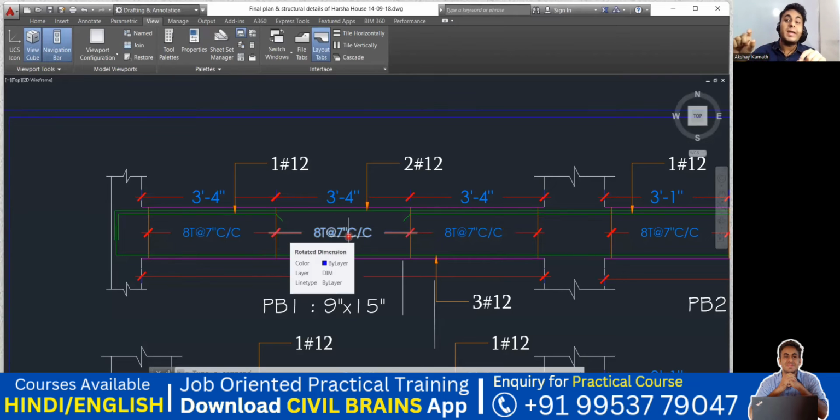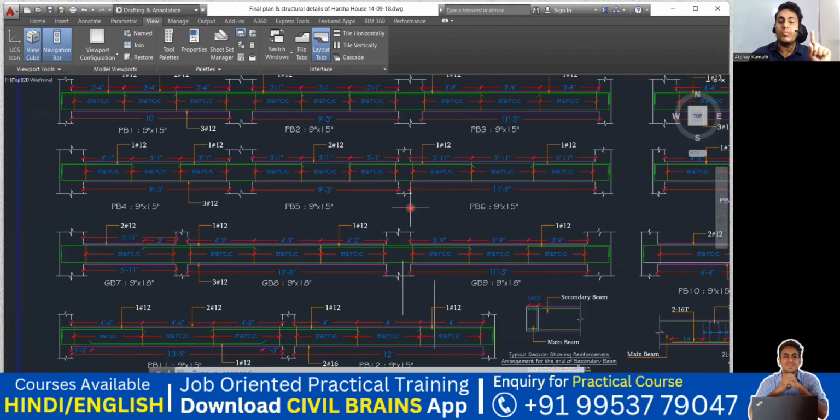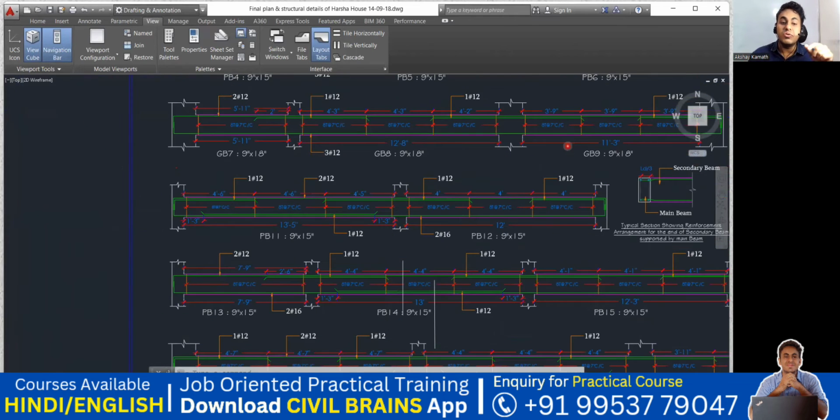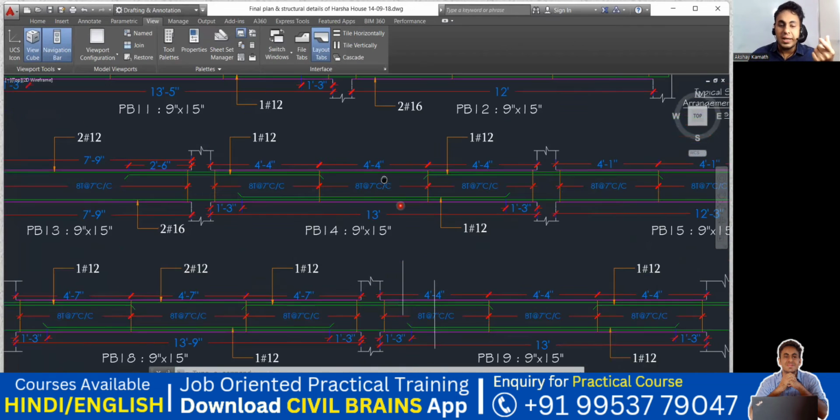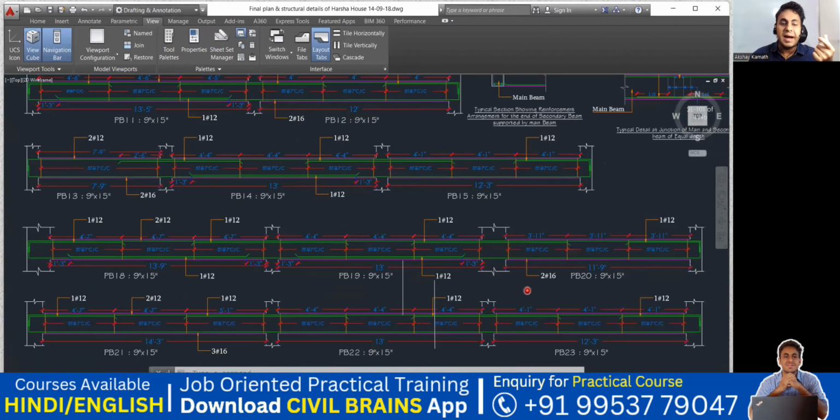So when the entire span is the same, why did they mention it 3 times? Basically, that doesn't happen all the time. If I show you some other drawing, that spacing will vary. In the left and the right support, it remains the same. In the center, we usually increase the spacing. So I think in this drawing, everywhere the spacing remains the same. So that is a pattern they follow.